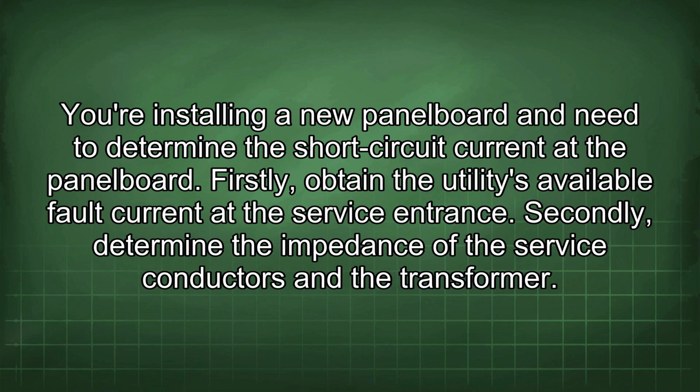Let's consider another scenario. You're installing a new panel board and need to determine the short circuit current at the panel board. Firstly, obtain the utility's available fault current at the service entrance. Secondly, determine the impedance of the service conductors and the transformer.